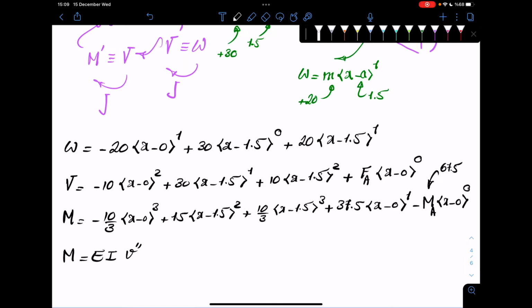And as I said, all you have to do is to integrate these 2 more times. I'm not going to do that. As you can see, it gets just longer and longer, but you get the idea. Now, integrating from this point on is very easy. And if you integrate more, you still get 2 more constants or unknowns. Again, let's call them maybe C3 and C4. But then you need 2 boundary conditions in terms of deflection or the derivative of deflection to get those.